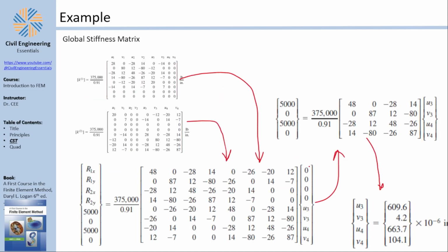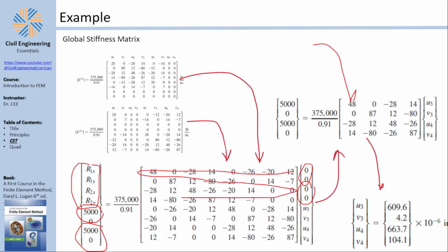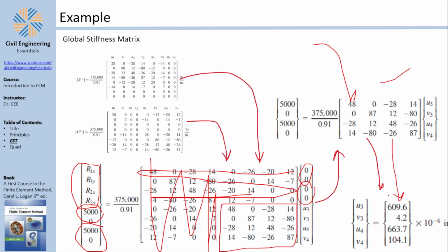Translating this, here you get a restraint in node number 1, a restraint in node number 2, unknown forces, which are your reactions at node number 1 and 2, as well as the applied force x only in node number 3 and x only in node number 4, which can be basically slashed, because remember, if you have zeros, you start slashing and dashing those rows and those columns. What remains is this block with the forces, and that's what you see here, which solves like this.